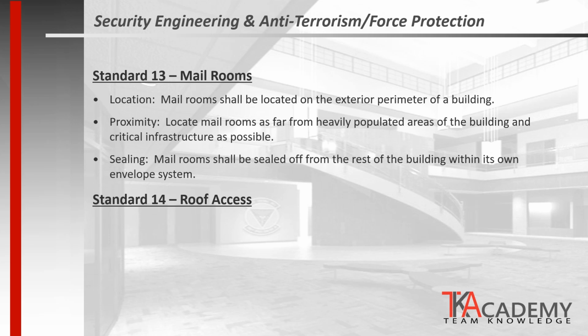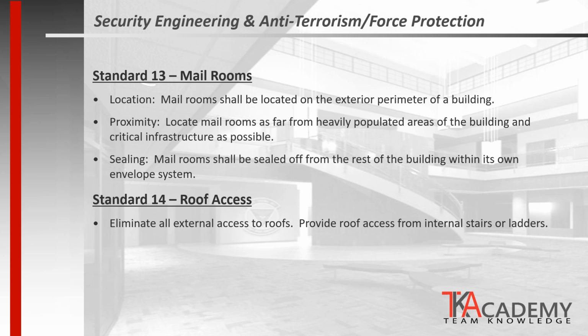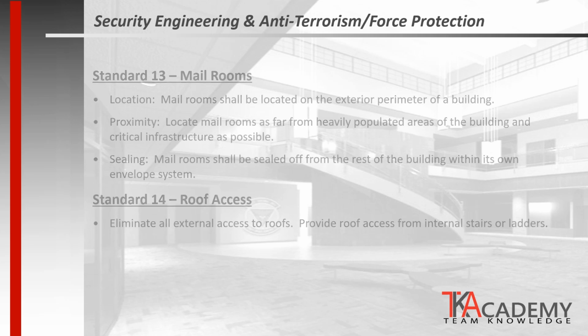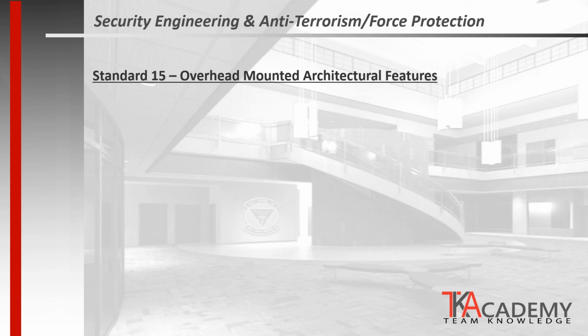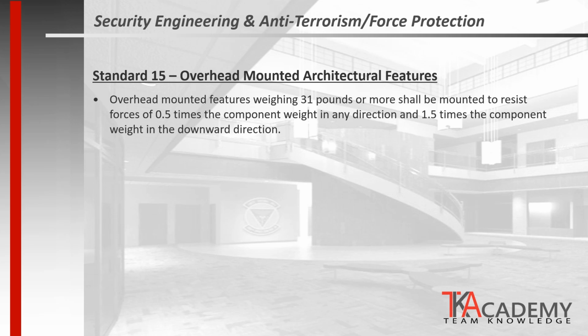Standard 14 addresses roof access. Its goal is to eliminate all external access to the roof and provide roof access only from internal stairs and ladders. Standard 15 is titled Overhead Mounted Architectural Features. Overhead mounted architectural features weighing 31 pounds or more shall be mounted to resist the force of 1/2 times the component weight in any direction and 1.5 times the component weight in a downward direction.